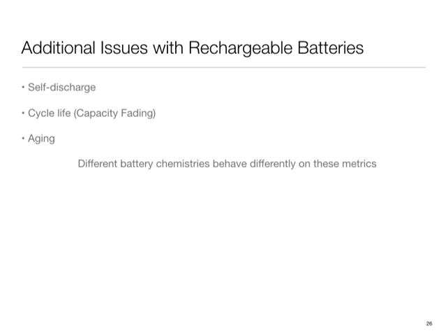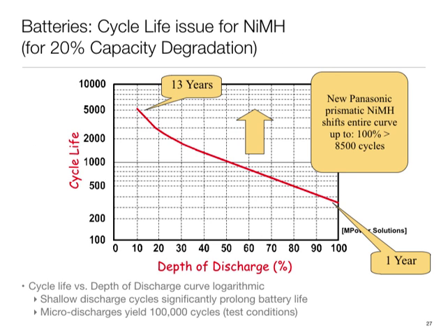So these are different effects, and again, different batteries are susceptible to different things. One of the big improvements in batteries is that the cycle life has increased tremendously, and that has led to manufacturers being perfectly comfortable just sealing the battery into the unit and getting other advantages like water resistance. I guess once the cycle life hit the 1,000+ point, that became possible. From what I understand, the batteries in smartphones are rated around 1,500 or so complete charge-discharge cycles. But complete charge-discharge cycles are not what we always do. Many of us do partial charge-discharge, and if that's the case, the number goes up.